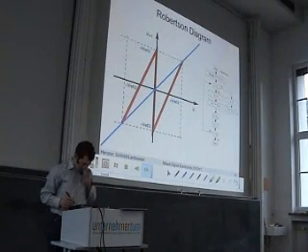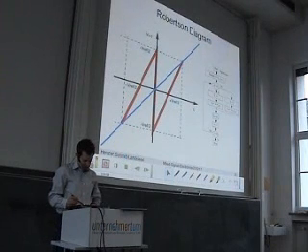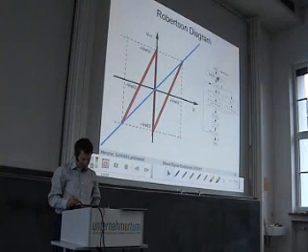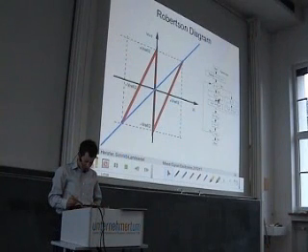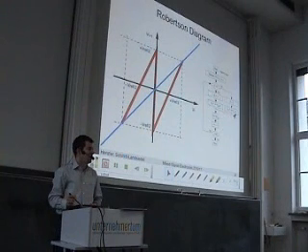Well, we have in this algorithm, this is a copy of the flowchart from the previous slide, we have always the case that we modify the internal voltage, which is first the sampled signal. We modify this in each cycle. We either decrement or increment it by Vref over 4.